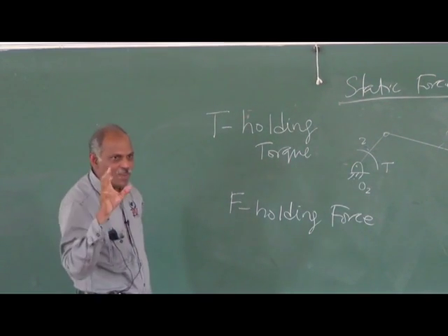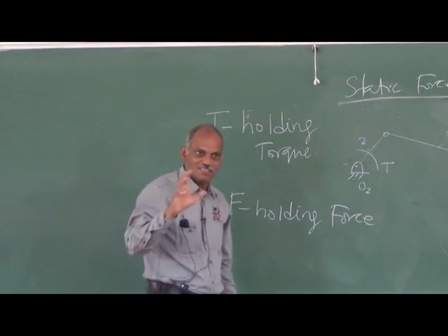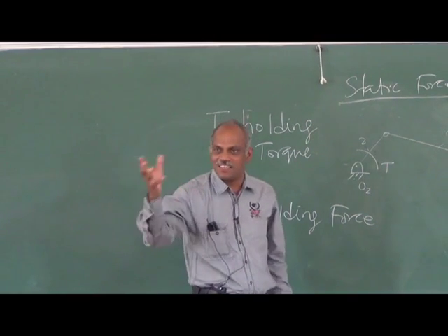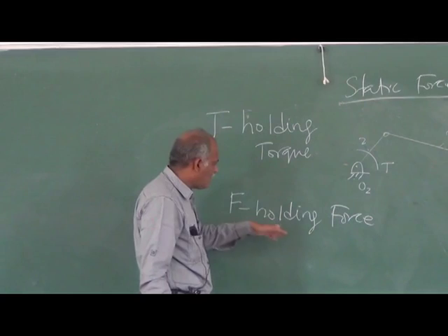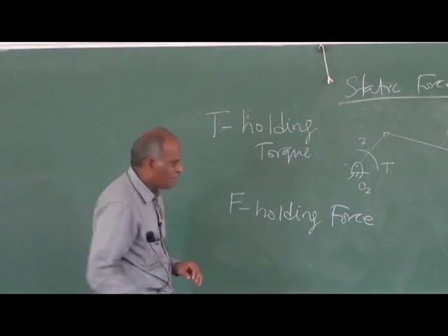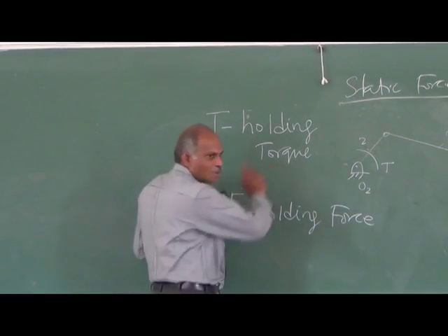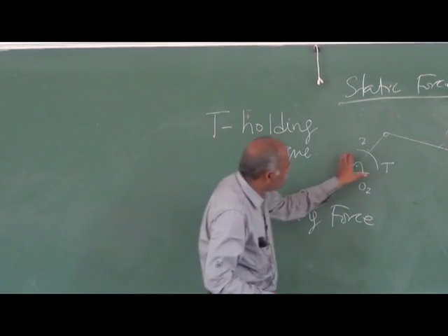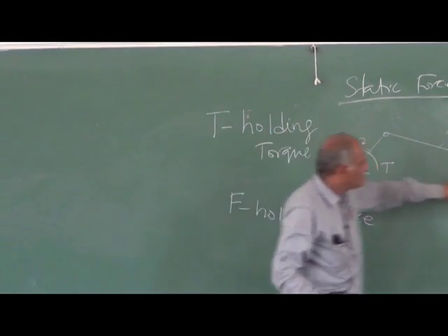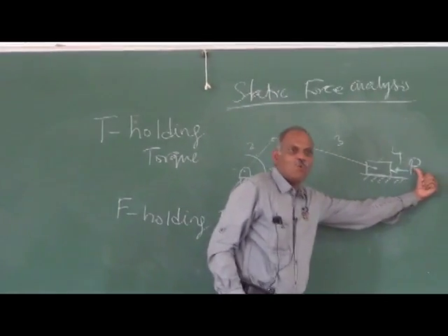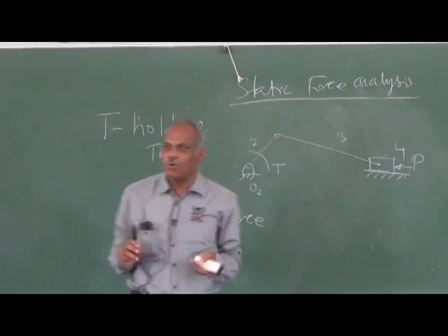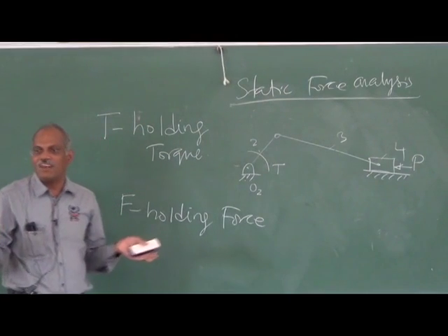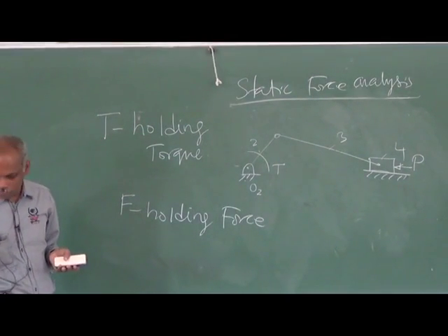So, if I apply a torque that resists the motion and makes the thing static, that is called a holding torque or holding force. In our case, this is a holding torque. Suppose I am offering a torque here and apply a force so that this mechanism is not allowed to move, then we can call that a holding force.